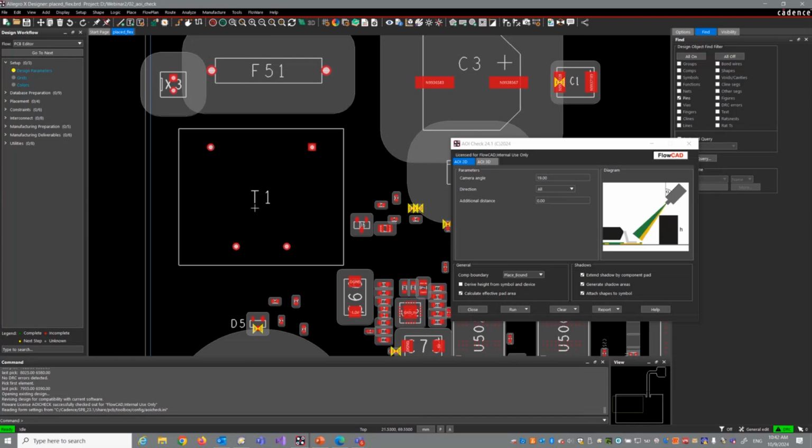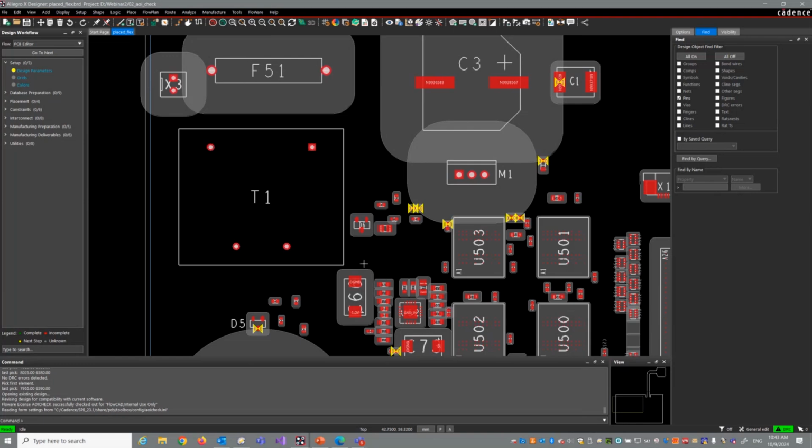This is just because this component will be manually assembled in the end. So there's no need to check this with respect to shadows. If not somehow disabled, it would generate redundant or false DRCs, which should be avoided.